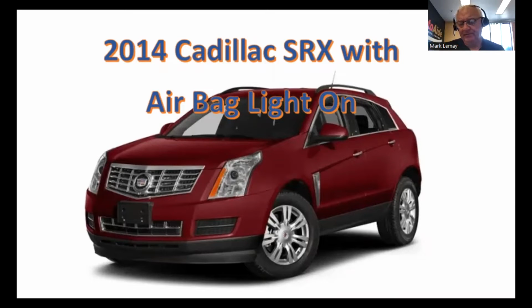sensor, which is nothing more than a sensor that detects impact on the door. Apparently, during the course of the repair, they replaced the sensor, so it's got a brand new door sensor in it. And after they put the door sensor in and powered the car back up, not only did they have an airbag light on, but now they had a code for the left door sensor and the left front crash sensor. So the problem actually got a little bit worse after they diagnosed and did the initial repair on it.